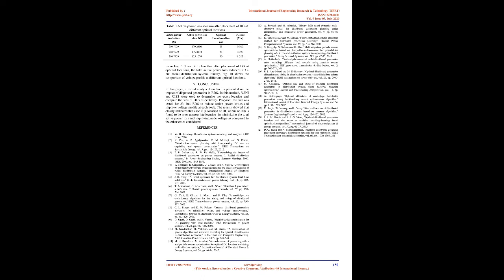To examine the efficacy of the proposed technique, it is applied to a 12.66 kV, 3.72 MW, and 2.3 MVAr RDS consisting of 33 buses. After application of load flow, the real power loss incurred by the system before placement of DGs is 210 kilowatts. To reduce the total power loss of the system, DGs are placed at different locations as shown in Table 3. The optimal allocation point is computed using equation 11. After computing VSNI at all buses, the 3 locations, i.e. bus number 25, 24, and 30, are identified as the most critical buses.